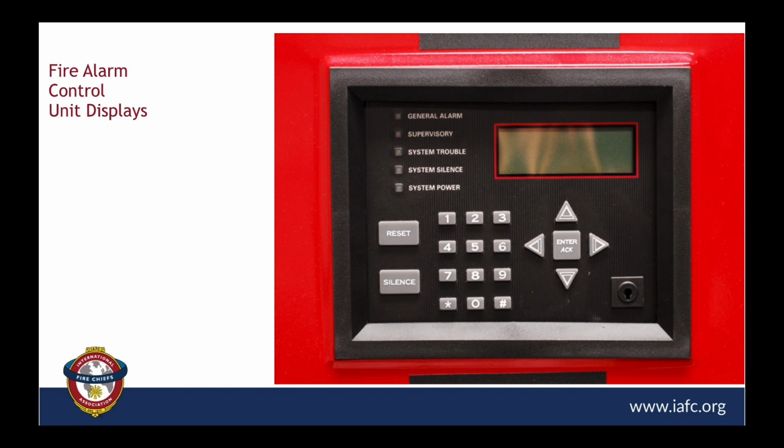What I've got here on these slides is a depiction of various manufacturers of control panels, and I believe there'll be many of them that you probably generally see in your field today. So I'm going to touch on the common areas, and I'm going to always start from the top of the panel and work my way down. You're going to see up here at the top, there's a general alarm LED. Then next to it is a supervisory LED, a system trouble LED, a system silence, and a system power.